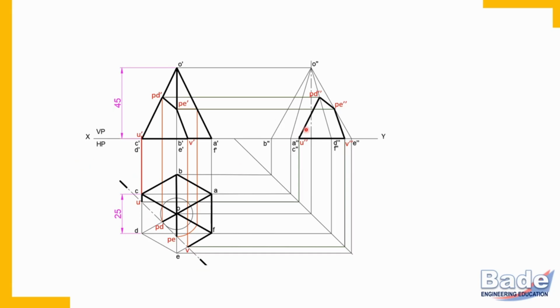This is cutting line. In the side view, this side is actually front of the object. When observer watches in this direction, it is having front view of the object, remember. When observer is watching in this direction, observer is having top view of the object. So this is front side, this is back side. This is top side, this is bottom side. Now check here. With reference to this, back side is retained. This is front side and back side. So back side, that is this side. Or you can use this logic. Apex portion is retained portion. So make this apex portion dark. Let's do that.